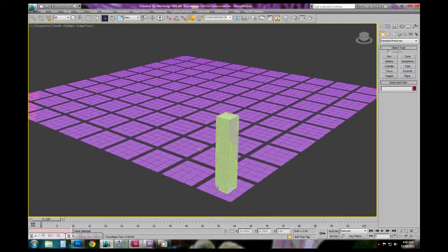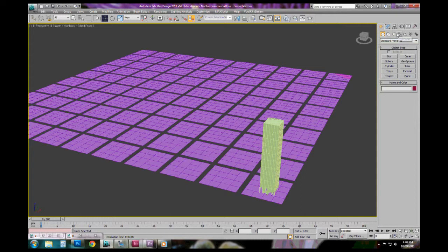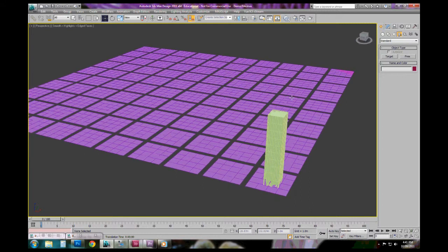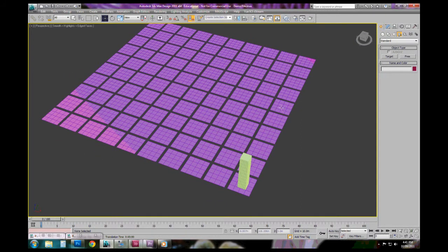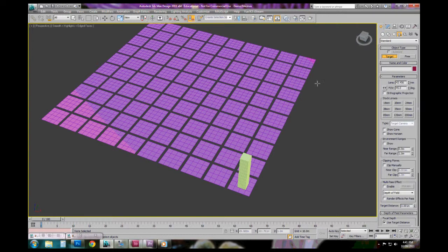So first of all, I'll go through setting up a series of cameras. Again, anything that has to do with actually creating objects, you always go to the Create tab on the command panel. Okay, and what we do is we just go over to Cameras, which is the fourth button across, and the type of camera that I'm going to stress that you use and continue to use is called a target camera. Alright, so what we do is we set up the scene looking through a camera which sets up the perspective that we want to keep.